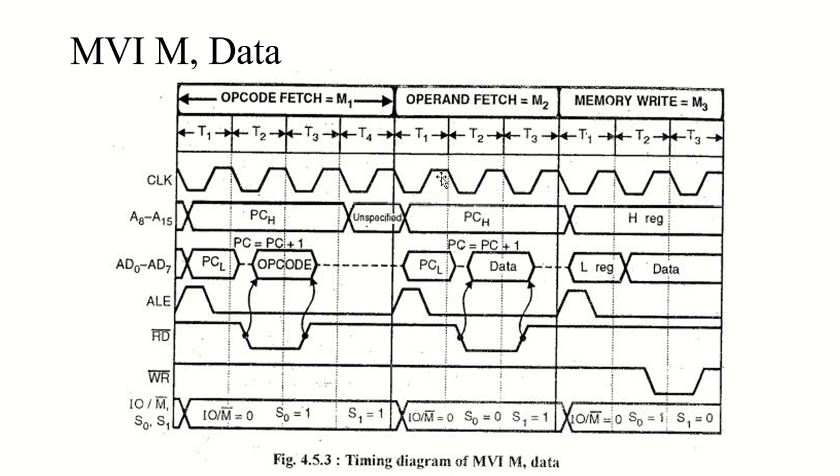So in operand fetch or memory read, it will again use the program counter to fetch the data from the program memory, like the data given within the instruction is read, so the program counter will be incremented by 1, and it will move to the next instruction, right? So that is what operand fetch is going to do.